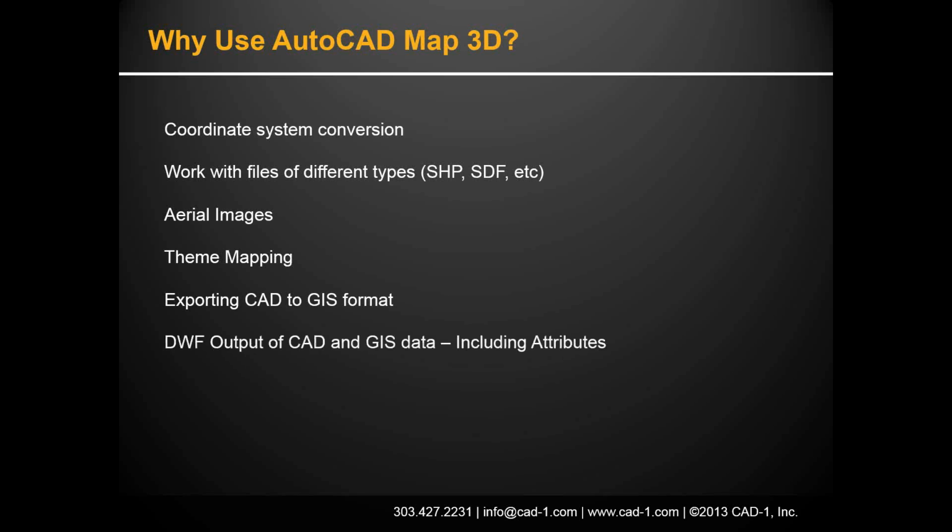Okay, another thing, I've got this really cool drawing with AutoCAD entities and with GIS entities and all these attributes and all this cool stuff. How can I give this drawing to somebody who doesn't have AutoCAD Map or even AutoCAD or AutoCAD LT, and they've never heard of AutoCAD? Well, something that people don't know is you can actually export it to a DWF file, similar to a PDF file. It's a free viewer, and you can embed all of your GIS data, all of your attributes, and all of that information, which is really cool.